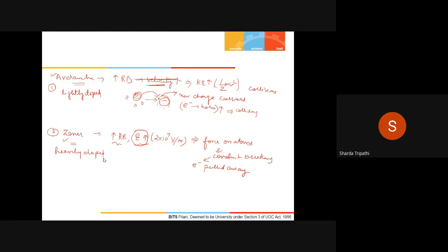This is another distinction. Then apart from this, in experiments it is observed that when the breakdown is happening because of the Zener effect, the IV curve that you see is more steep. So this will be almost a steep curve in this way. Whereas in case of the avalanche effect, the curve is not that steep. So it will be slightly like this. This voltage can be approximated as constant voltage, but this is not as steep as the curve observed in case of the Zener effect.